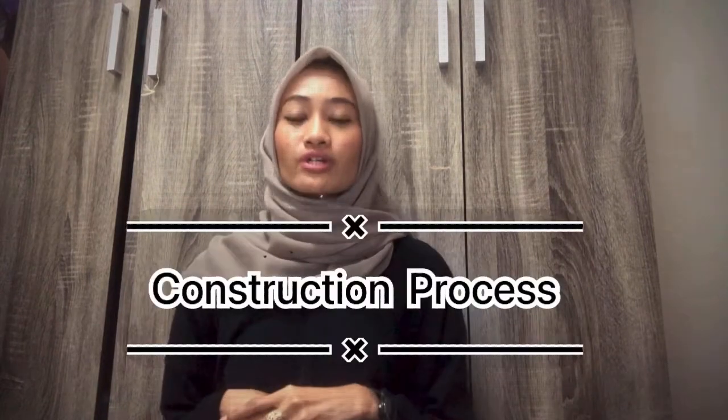Next I will proceed to the construction process. This part discusses the construction process of precast concrete framing for the 8-story academic block at UTHM. The engineer, architect and contractor were involved to fulfill the requirements of constructing the building. The suitability of construction materials for the purpose of use includes sealant, grouting, shimplate and propping.